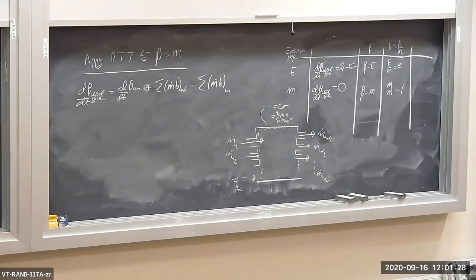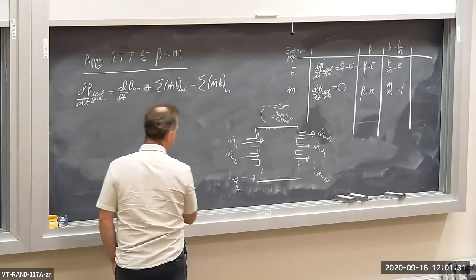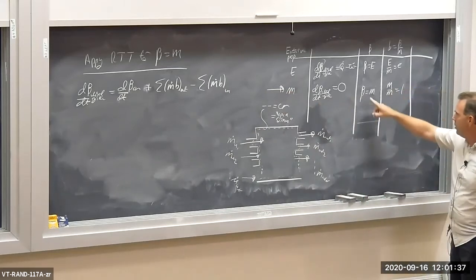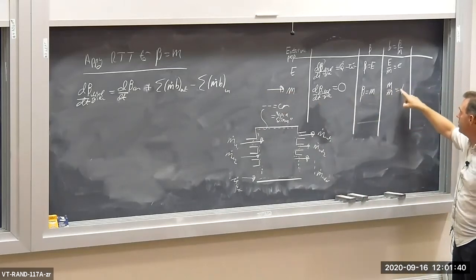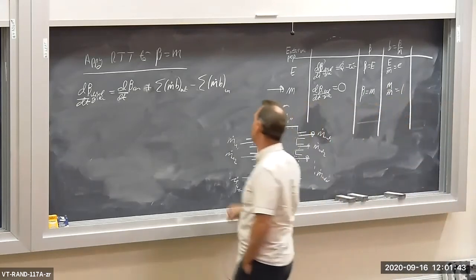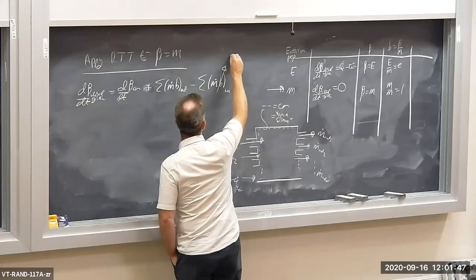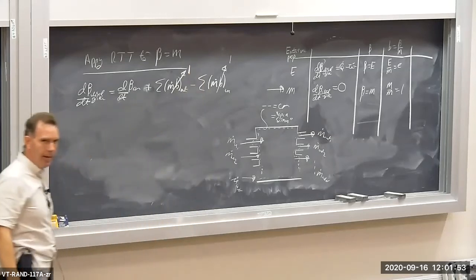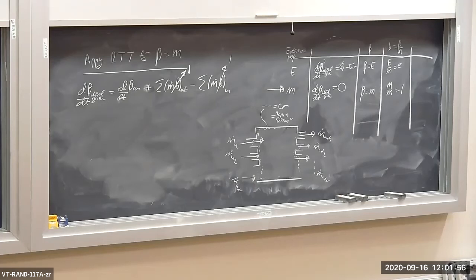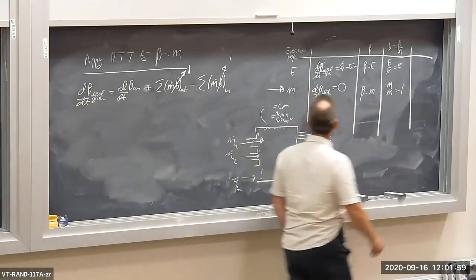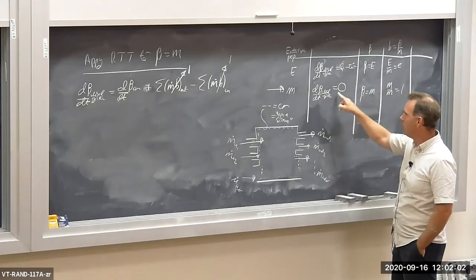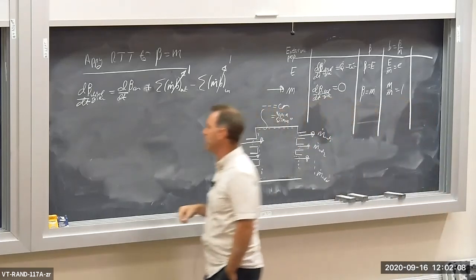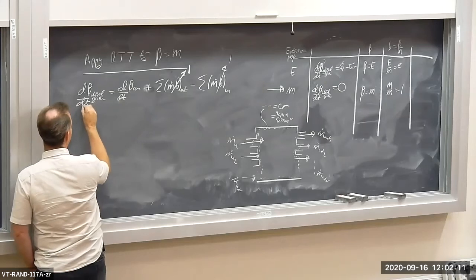So there's Reynolds transport theorem. Let's apply it to mass. Well, beta per unit mass, b, is 1. So these b's here in the flow part of Reynolds transport theorem become 1. Okay? Beta per unit masses, those all become 1. d beta dt for the closed system is equal to 0. No change in mass with respect to time for the closed system. So this term is 0.